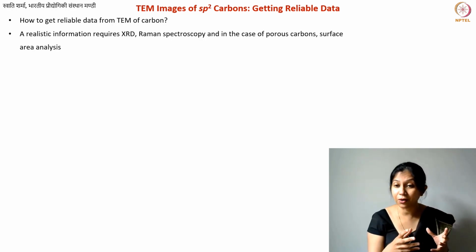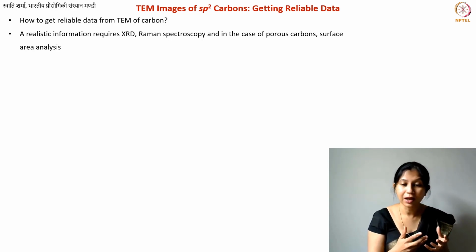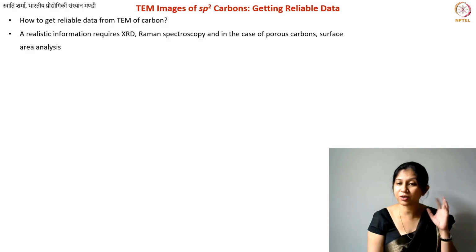So this gives you information, and this information can also be deduced from the density of the material, because for example these non-graphitizing carbons are very low density materials. So in principle they should have some porosity, but at the same time they are impermeable to gases and liquids, which means you have pores but closed pores. And closed pores are also not really visible, so you can also not evaluate them using other porosity measurement techniques. So it's really difficult to understand them. TEM in that case has been really helpful.